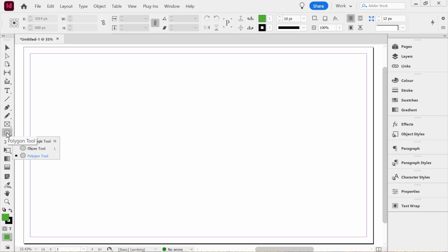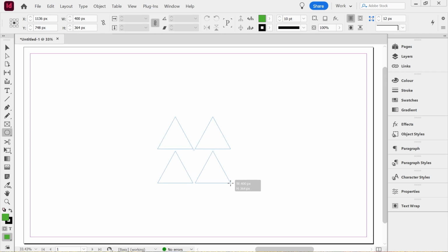Finally, we're going to look at the polygon tool, which is a little bit different. Say, for instance, we drew this triangle, pressing the up and the right keys will obviously do that, right? So if we want to increase the number of sides, we have to basically tap the space bar, and then we can go up in the number of sides. So say we go to a hexagon, we can press right and then up. And that way you can choose how you want the shape to look.